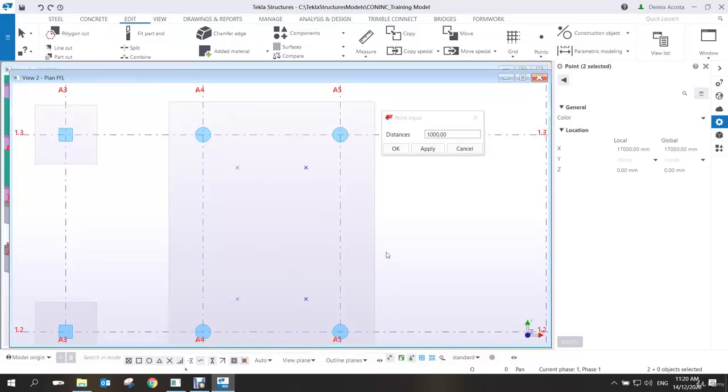You can move, you can copy, or you can just simply use the construction point. Whatever you want, you can do that one. Again, you can do this in the 3D view, but what happened here is I just simply opened the plan FFL so that I don't have any interfering views or objects. So you can press Ctrl I and then open the plan at FFL.